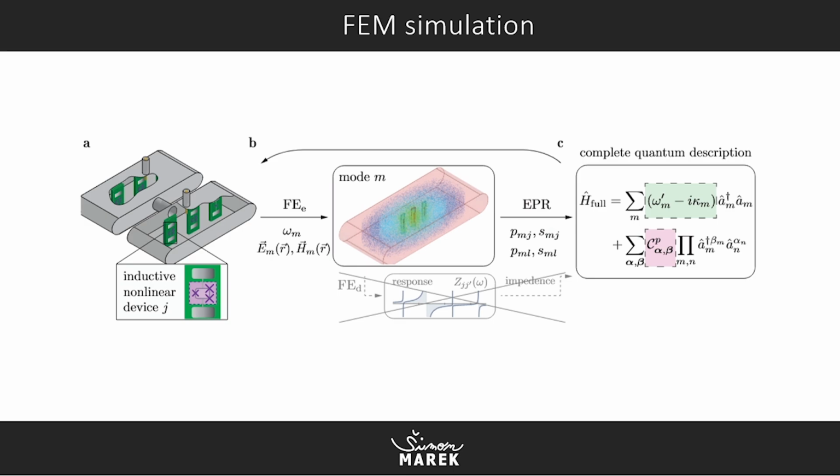Next, we have FEM simulation. We are talking about EPR, which is a technique to evaluate the quality of quantum chips or Josephson junctions. Here's basically the workflow for this technique. We need to use a FEM simulator which is compatible with EPR.